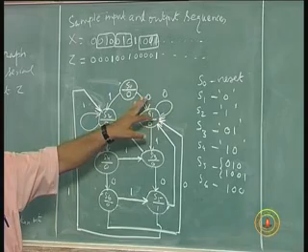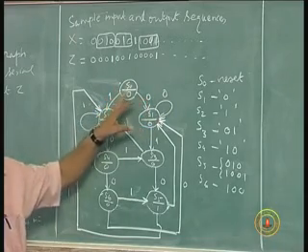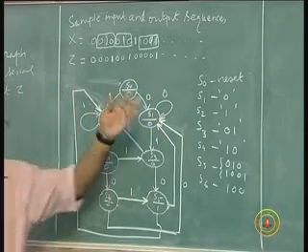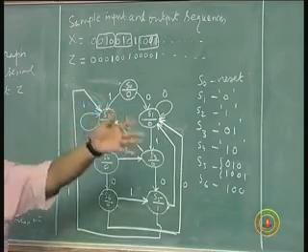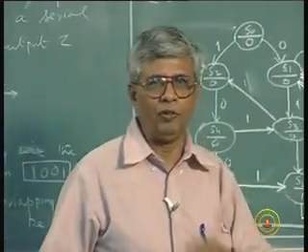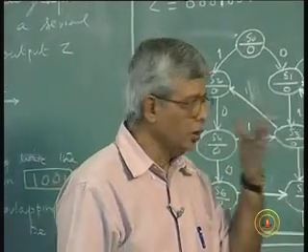So the input x is equal to 0. What is the next state? Input x is equal to 1. What is the next state? Then for each of the present state, you write the output. That becomes the state table. And depending on the type of flip-flop, you can do the transition table and finish the hardware.